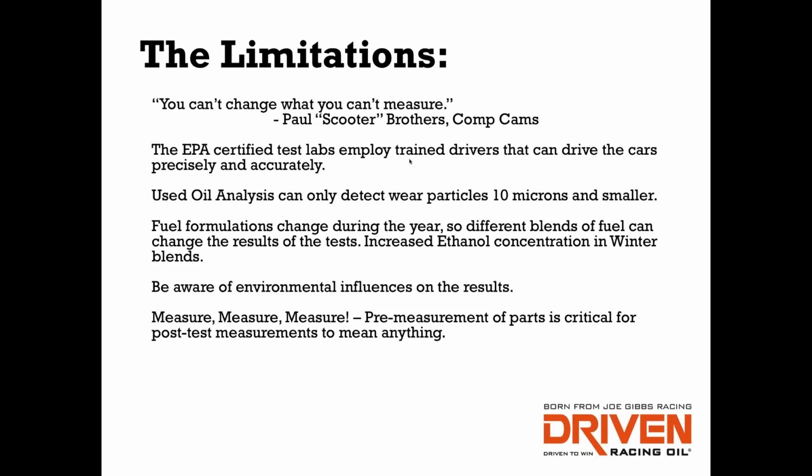Again, measure. You've got to pre-measure parts so that you can post-measure parts. If you don't have a pre-measurement and you post-measure it, it doesn't mean anything. You've got to know what it was before and what it is after, and you've got to be precise and have a methodology. We're going to put that part in this room at 72 degrees Fahrenheit and keep it there for 24 hours, and then we're going to measure the part. We're not going to take a part right out of the dyno and measure it. We're going to make sure the parts are measured at the same temperature, the same way, on the same equipment. You follow the procedures to eliminate variables that can throw you off. That's important.